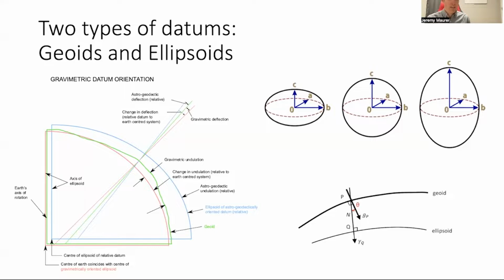And in fact, it's going to turn out that the surface of the Earth, where we define the surface of the Earth, called the geoid, is based on basically having an equal value of gravity everywhere along that surface. And as you might imagine, if you have mountains or valleys or really dense rock masses like ore deposits, those kinds of things can actually change the value of gravity locally, or change the direction of gravity locally to that area. Around the mountain, there's more mass there that causes a higher gravity value. And so actually the geoid, the shape of the Earth, looks a lot more undulating, a lot more variable than the ellipsoid reference frame or datum looks.